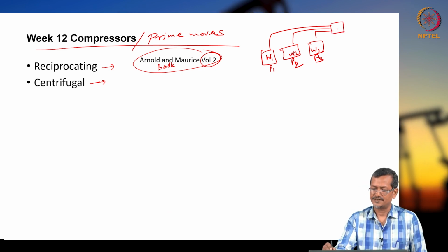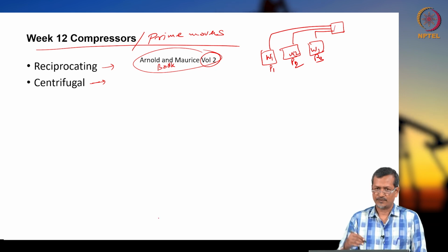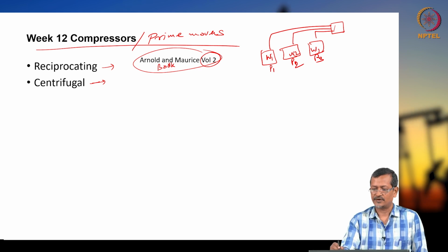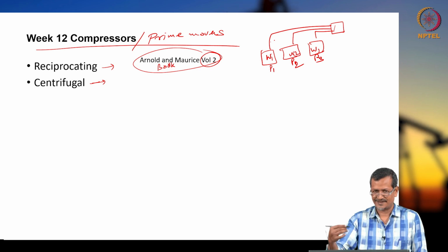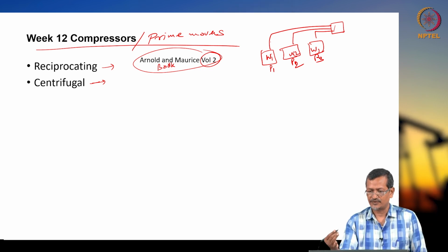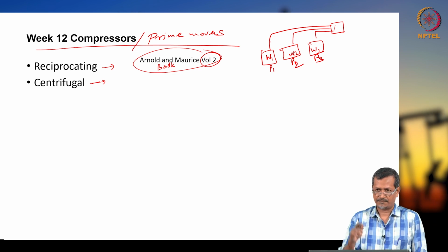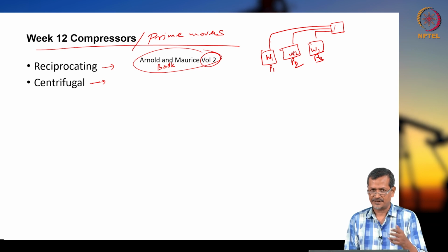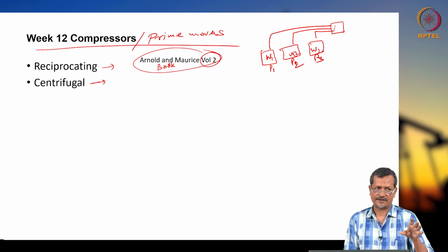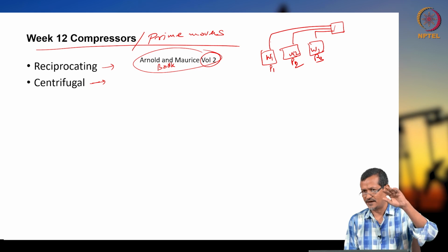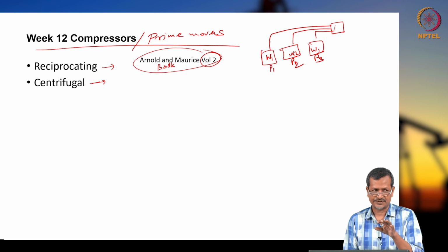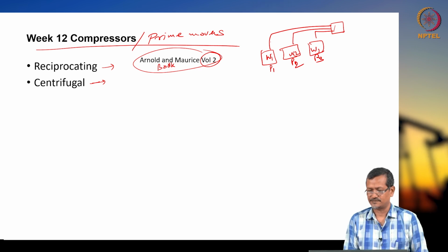If you are not managing this gas pressure properly, what will happen? P1 gas may enter into P2, or the P2 production rate will be lowered, because high pressure will push against the low pressure. So maybe you have to use a booster pump so that all pressures are equal, then you can have a common line and a common separator system. Even for pumping systems it is the same: if one is very low pressure and one is very high pressure, you will have difficulty in surface production systems. So you need compression or pumping systems.